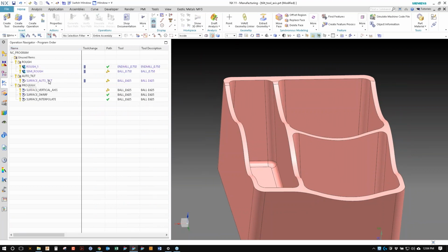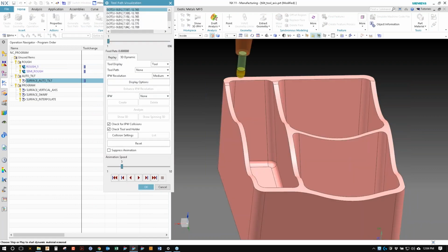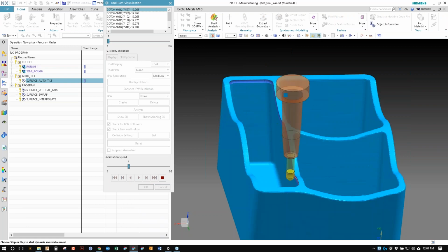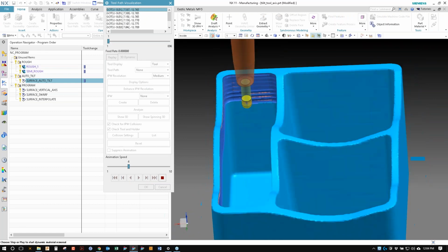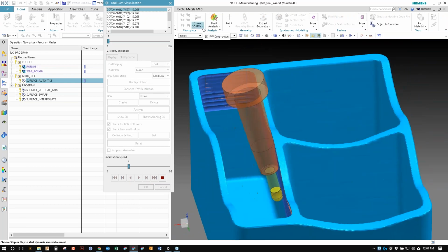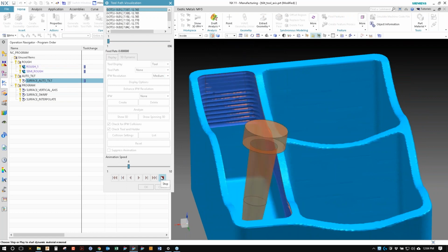And that allows me, without having roughing toolpaths, to show material removal without having the pocket full of material. Basically, so here's 3D dynamic where it will show that material. So there's the 60 thousandths of material offset from part being removed. And of course, your step downs would be finer, but just for the sake of processing time, I have the step down pretty rough.